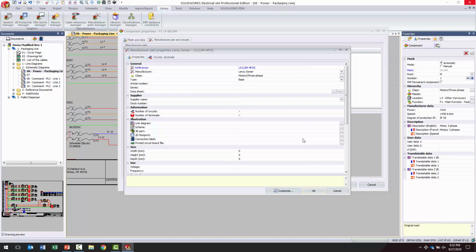By doing that, what you are doing is you are now putting it on one instance and then changing the library. Well, how do you get it to the rest of those devices? And here's what we have is called update data. I'm going to go ahead and do that for this one here. Maybe I'm going to change the height, width, and depth. So maybe this device is, we'll say it's, I know these are fictitious millimeter numbers. These aren't anywhere even close to the proper numbers.